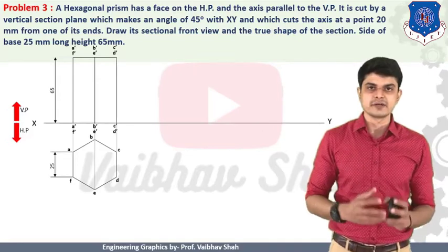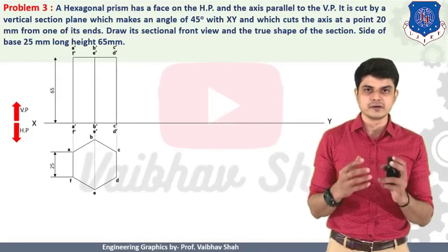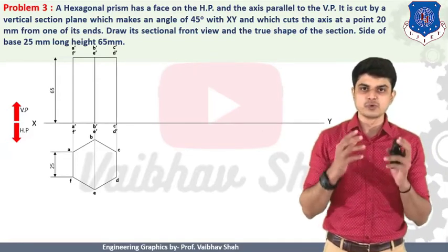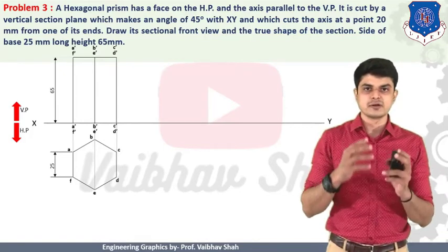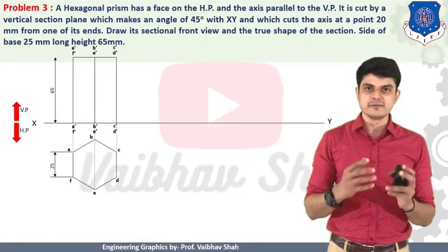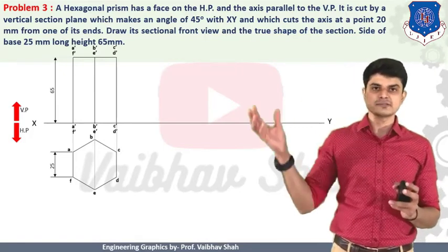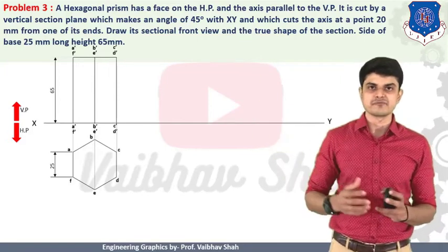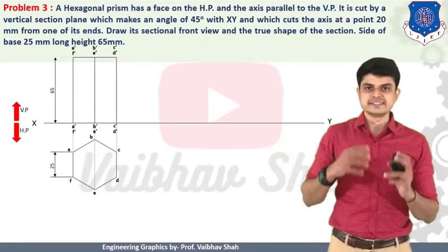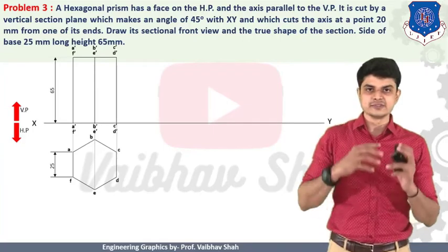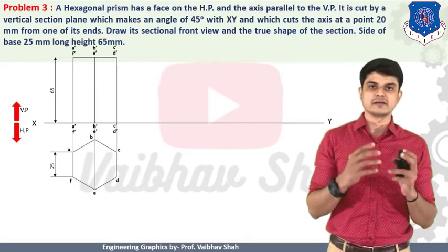So this is nothing but a hexagon related, and always remember, a hexagonal prism has two of its faces superimposed or coinciding each other, so we'll be having a double dimension to its sides, the top face and the bottom face dimensions. Now, in second phase, it is said that it is resting on one of its rectangular faces.